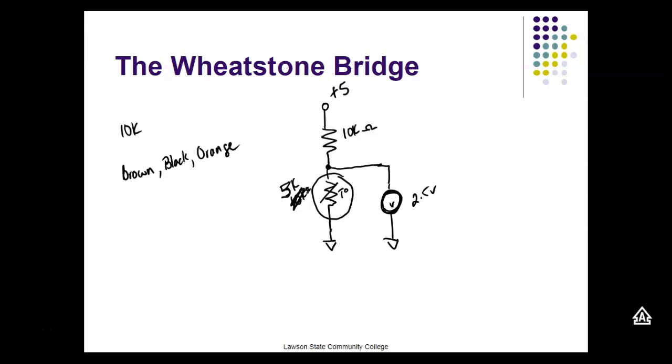You can't go up when the resistance is going down. When your resistance goes down, voltage drop is going to do what? In a series circuit, if resistance goes down across a resistor, so what you're saying is a 10K would drop more than a 5K in a series circuit. Yeah, so some of these things you've got to reason out and understand when your answer has got to be wrong.